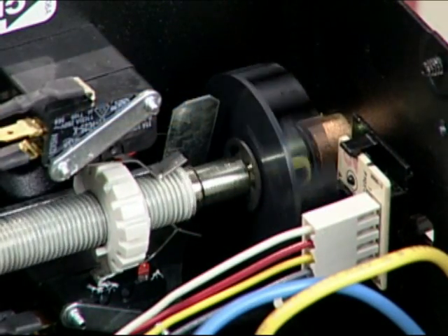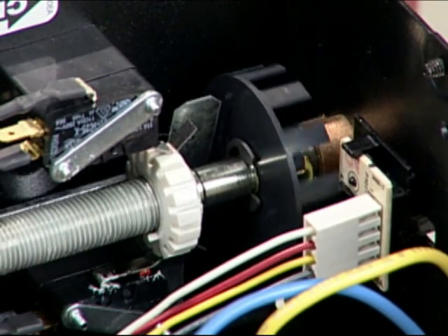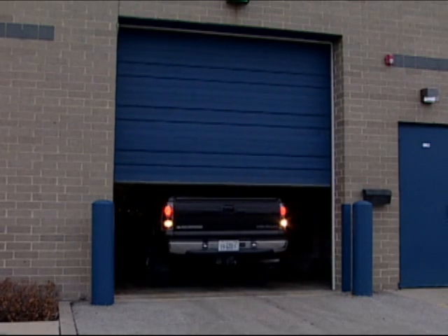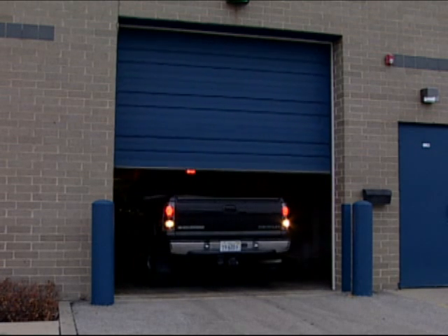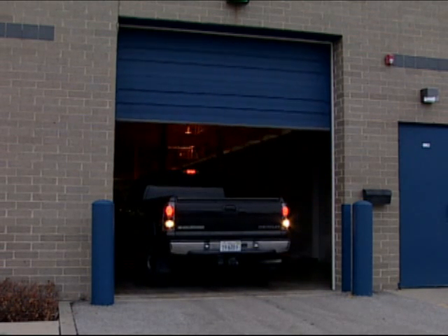The RPM sensor feature on the Logic 3.0 control board is automatically learned and does not require programming. This feature utilizes an RPM sensor as an auxiliary reversal system that reverses the operator upon hitting an obstruction in the down direction and stops it in the up direction, thus preventing excessive door and operator damage.